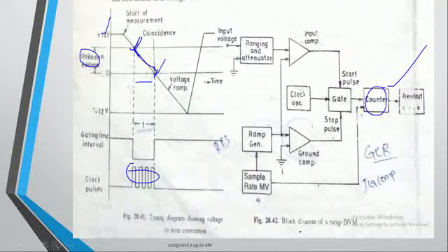From there, I'll take this as one locking point. I can say that it is the starting of the gate. At the point where these two signals have equal magnitude, that point is called the starting of the gate, and it will close the gate. This switch is in the starting mode until the ramp signal crosses the zero level.